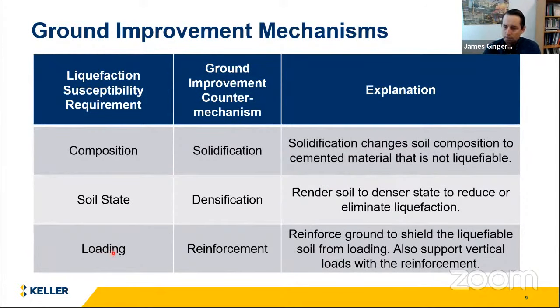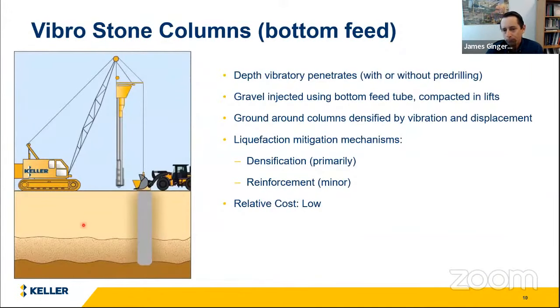And then loading, we can alter the loading by reinforcing the ground and having the ground improvement take the shear loading and shielding basically any in situ soil that's between the ground improvement from receiving those higher seismic loads and therefore mitigating liquefaction. So here are a few techniques.